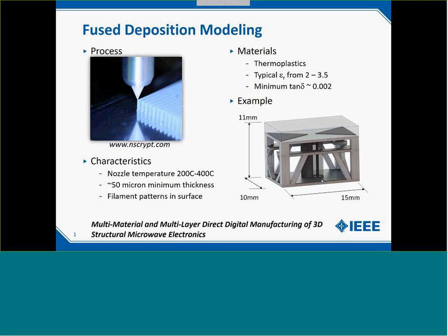Materials, as I mentioned, they're all thermoplastics, and typical commercially available materials have dielectric constants in the range of 2 to 3.5 or maybe up to 4. And one very nice thing about FDM and the thermoplastics for microwave applications is that you can achieve very low loss tangents on the order of 0.002.